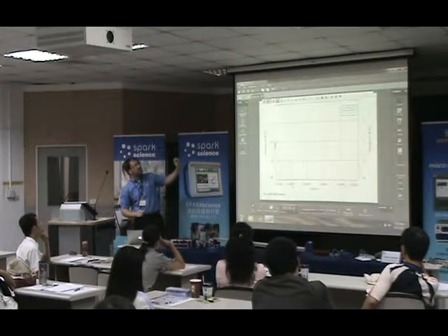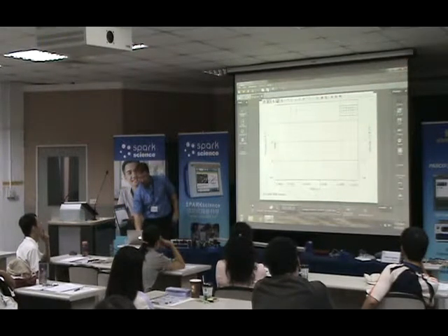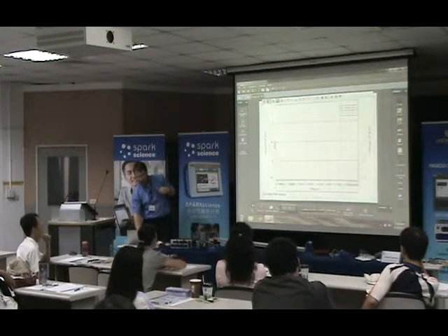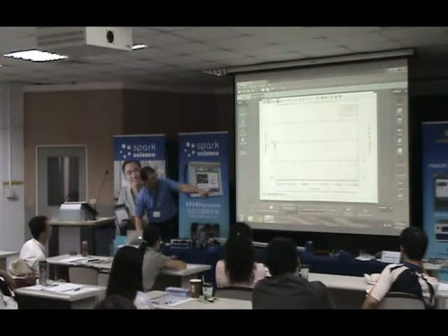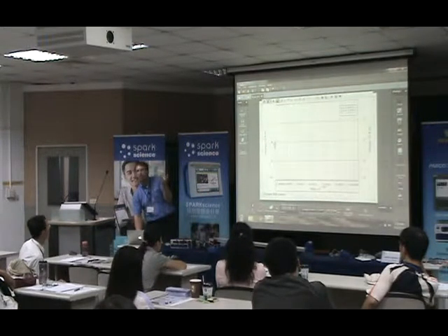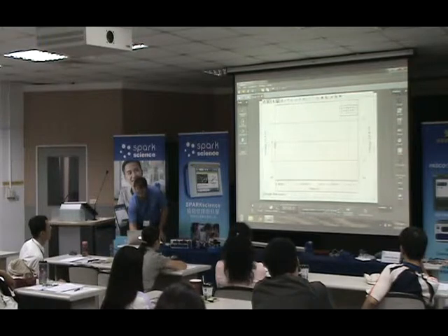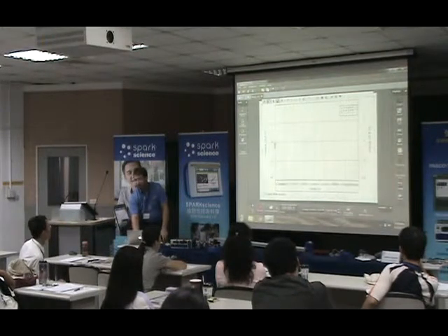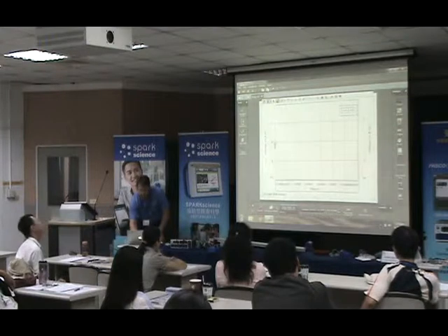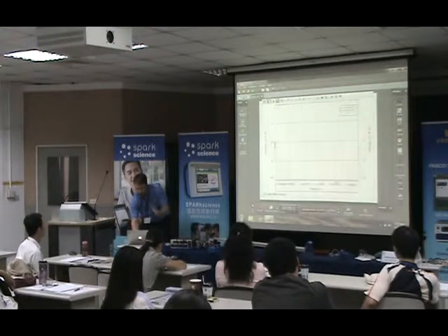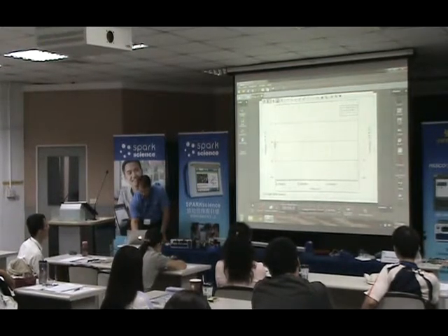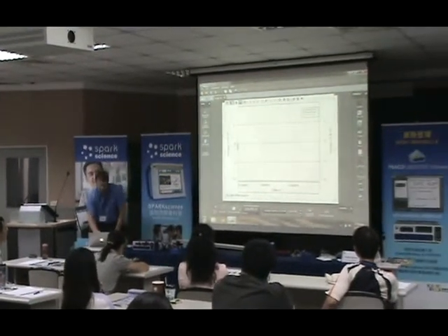And you'll notice one nice thing Capstone's going to do for me as I do this is I know roughly the time period I want to look at. But notice at the bottom of my screen here, Capstone's adjusting the sampling rate to make sure that you have plenty of data points depending on that time window. Okay? So I'm going to go ahead and just comb through, and I'm going to get it to where my sampling rate's roughly 5 megahertz. Okay? So this is a really fast looking at a short amount of time with lots of data. Okay? So there's 5 megahertz right there.